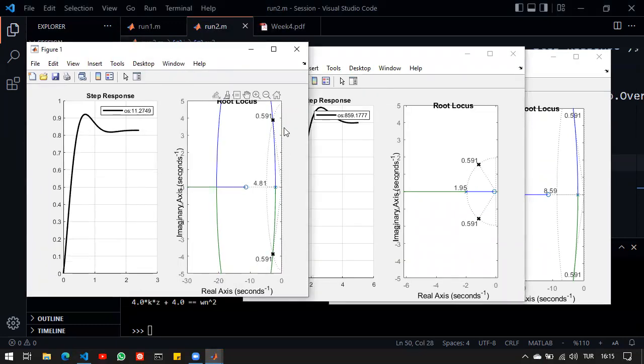Now we can see that our closed loop poles are exactly on the root locus plot, and we've also added a 0 here. This means that we've basically updated our root locus by adding a 0, which is expected because it had only 2 poles, and a root locus based on 2 poles is different than a root locus based on the 0 and 2 poles. So we did change the root locus plot by adding a 0, and we've chosen exactly this point, which should be the k value for this solution. So gain is equal to 0.42 in this case.